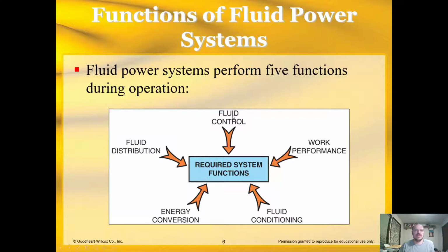It doesn't necessarily matter the way they built this, but fluid control: we have to control the circuit itself, the amount of work done, right? Work performance, fluid conditioning, energy conversion, going from hydraulic to mechanical or mechanical to hydraulic, and fluid distribution: how is that fluid getting distributed through the system? So those are the 5 required system functions to have a fluid power system.